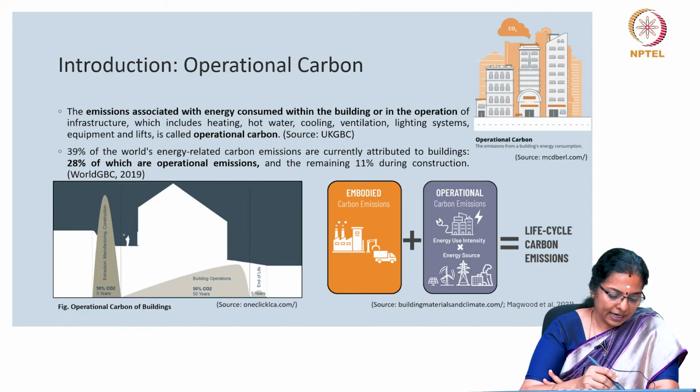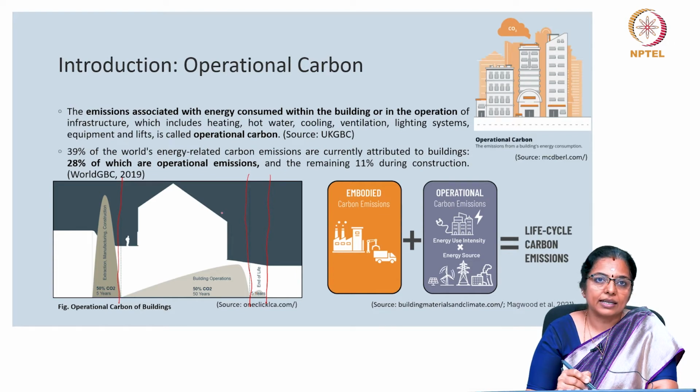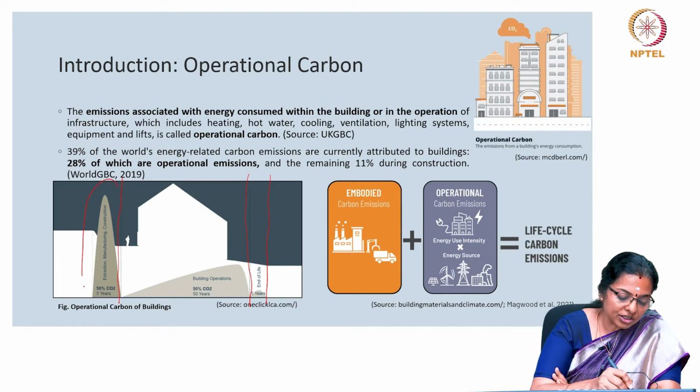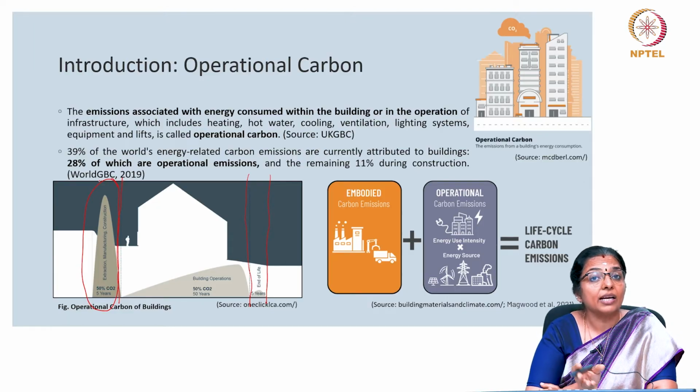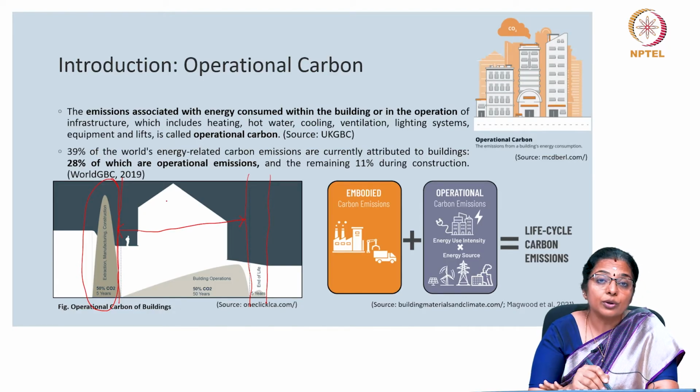So, we already know that there is something called embodied energy, and there is something called operational energy, and there is something called end of life energy. You need to understand that embodied energy is applicable during the construction of the building and before the occupancy of the building, whereas operational energy is all the energy that the building consumes when people use the building.